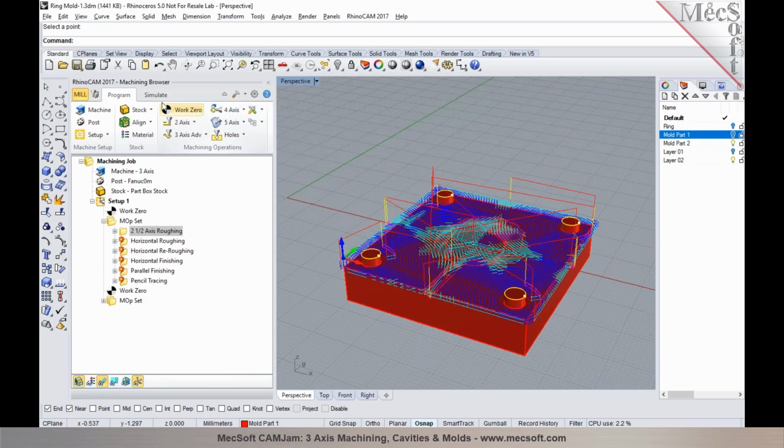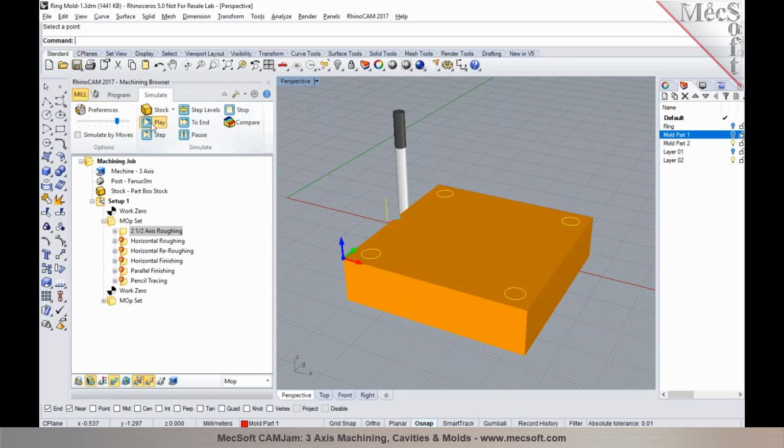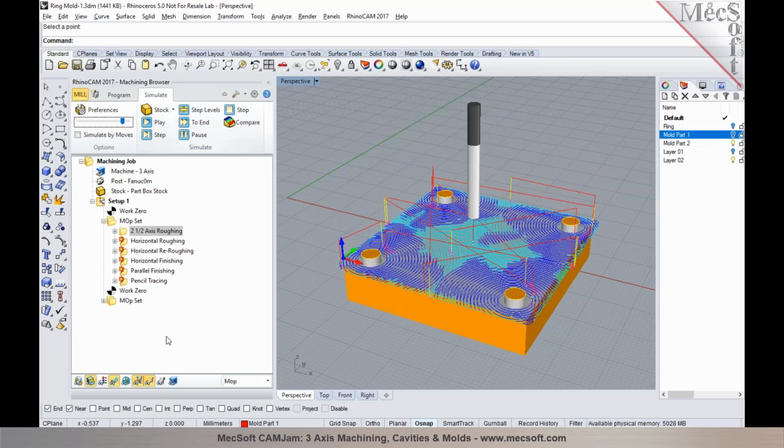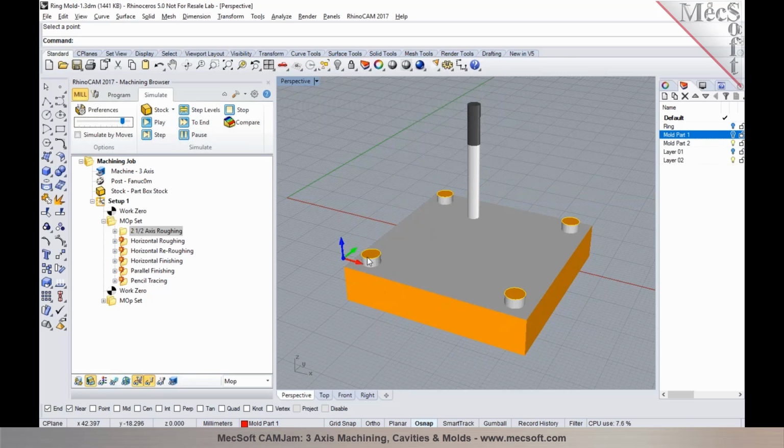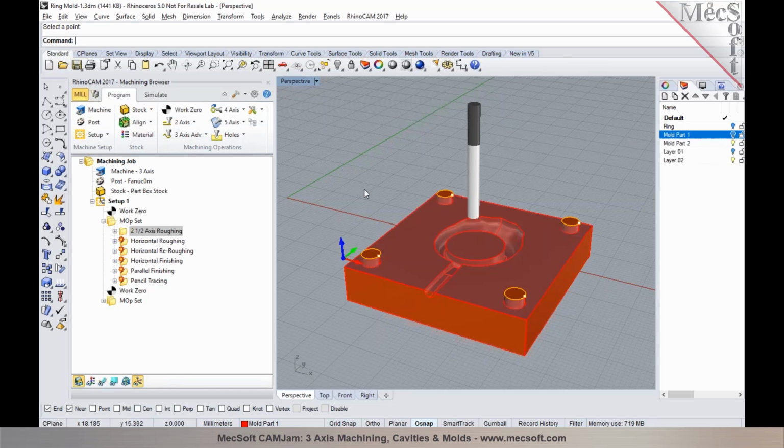Thank you, Joe. So we now have the roughing operation programmed in here. This is very similar to roughing in 3-axis. However, here you're using a roughing for 2-axis operation, ideal for prismatic parts. And as Joe pointed out, this automatically takes into account the extents of the stock that you defined. In this particular case, it just happens to be a rectangular stock, but if you're using a stock with any other shape, cylindrical or any odd shape, it'll automatically take that into account.